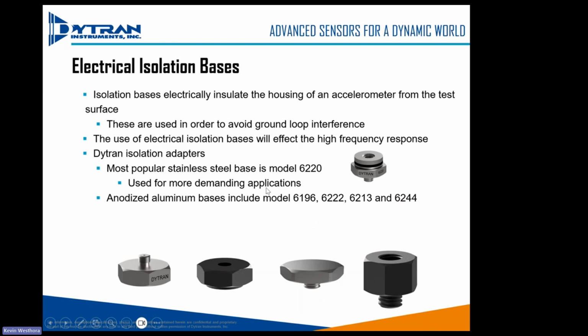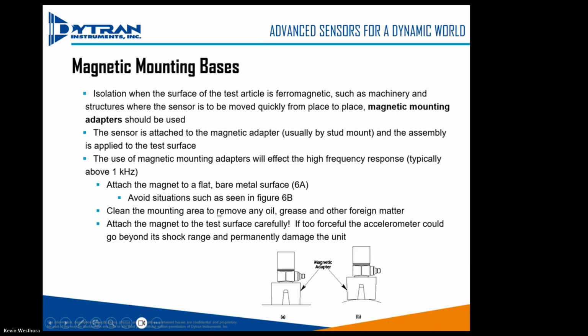Now, even though there's only 3 ways to mount an accelerometer, that ignores the fact that many customers use a base. Whether they're going to glue it or whether they're going to stud mount it, they would rather use a base because that's your sacrificial part. It's much cheaper than breaking an accelerometer. If you're going to be putting it on and taking it off quite often, you'll want to use a base. We make hundreds of different bases at Dytran. Okay. Curved mounting. We also use magnets for curved mounting surfaces and things like that.